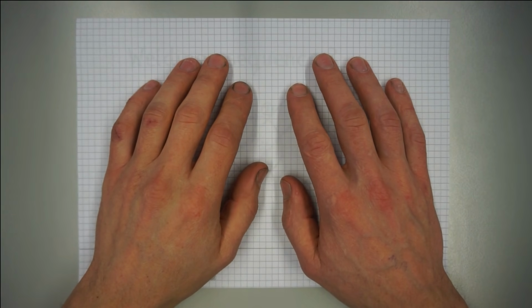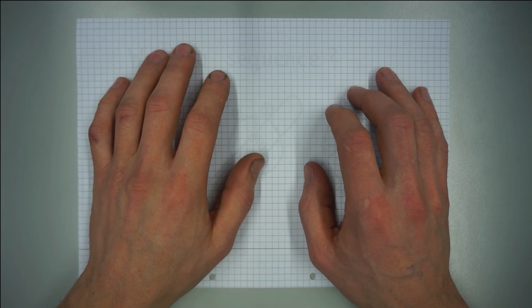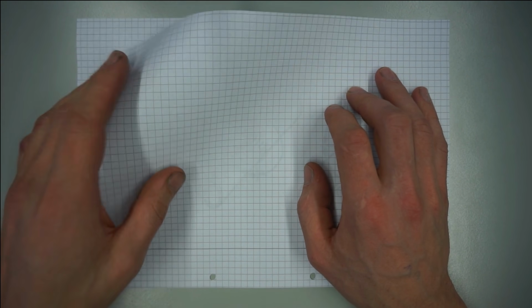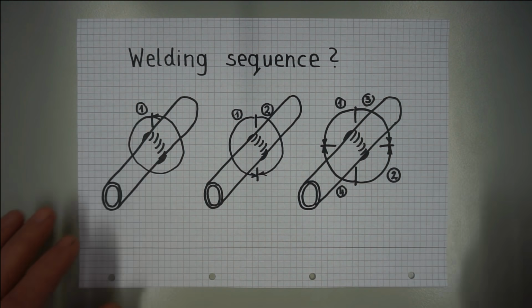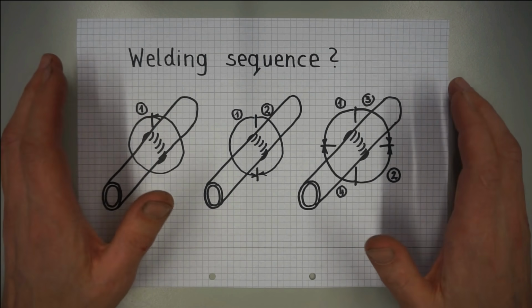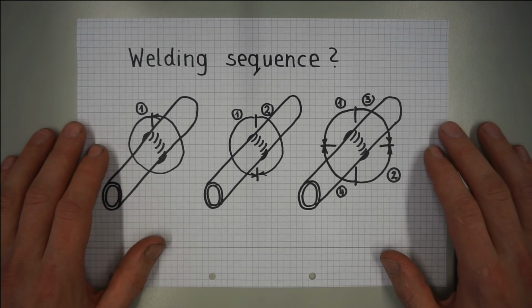At this point you may say, wait a minute, didn't you forget to mention reducing distortion by coming up with a smart welding sequence? Many welding books advise that. Actually, no. Because a good welding sequence gives low distortion because it implements the 4 previously mentioned strategies more or less simultaneously.